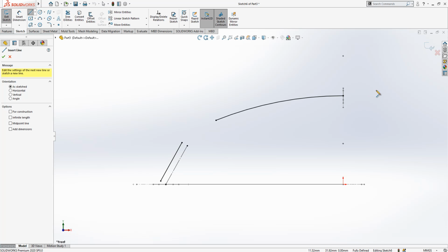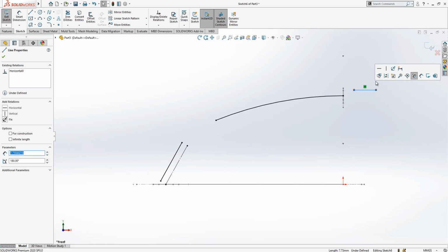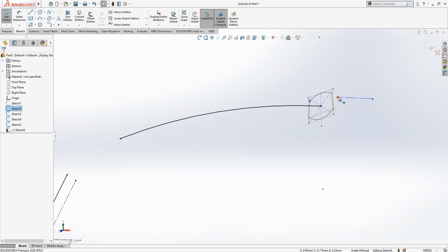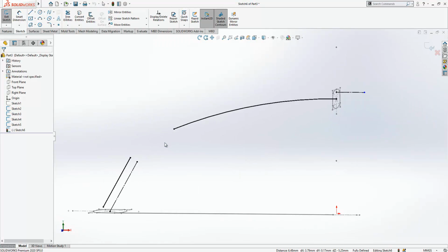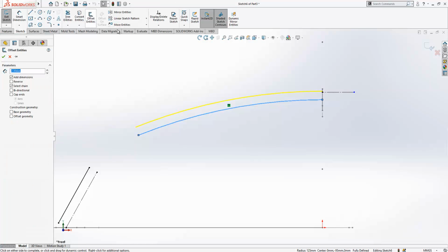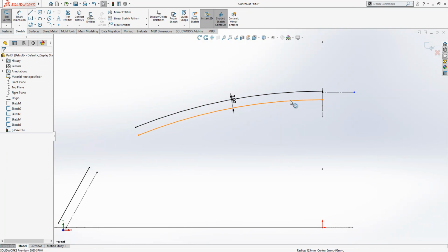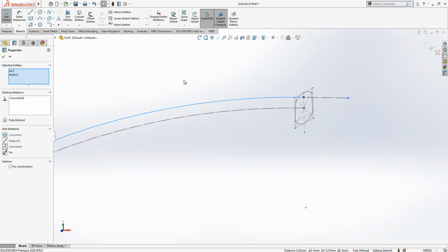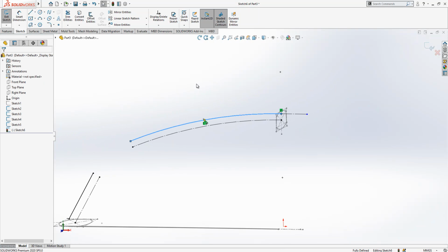Now again, same idea. I open a sketch, a new line here. I will combine these two lines, coincident. Now I look from front. I will make an offset. Two is there. This should be here again, coincident. This tangent, two points and coincident.